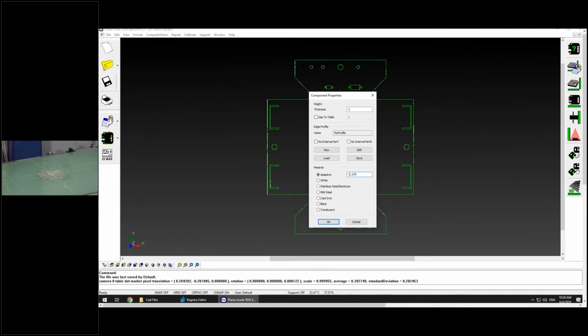So adaptive is there for that reason. When in doubt, if you're ever going to use an adaptive, just leave it at 0 so that we don't change any numbers. But if you guys want to go through, you could use adaptive in that way and actually change it per program. So then what I do there is, let's say this part passes better with 0.5 adaptive value, then I go in and grab this part, and then all of a sudden as I run this, I know that maybe 0.125 runs better. And you just have to save that in the planar file as the adaptive setting, and then you're good to go from there. All right, so that's what the adaptive does.